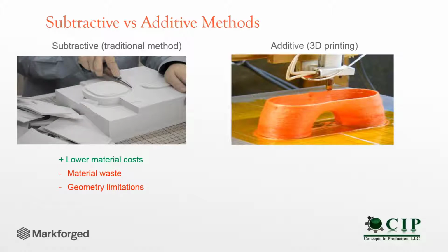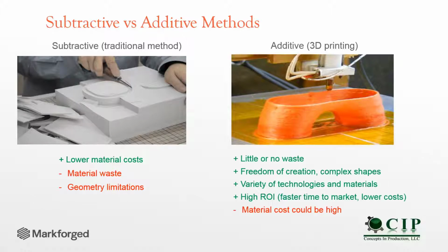Now additive manufacturing, or 3D printing, benefits because there is very little waste as the part is built layer by layer. The waste there is support material, and that allows you to make complex shapes. You just remove the support at the end. And one thing we'll talk about and show later is you reduce the support by designing your models to not have it, and that'll save you material waste and money in material cost.